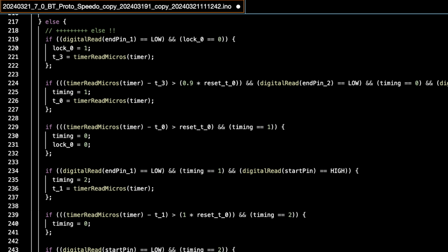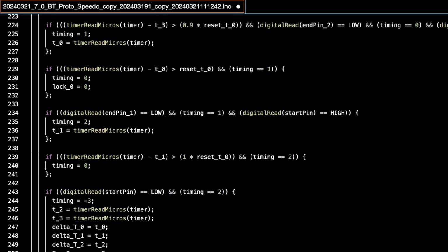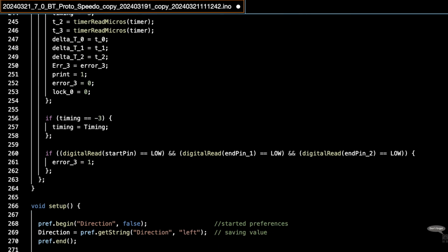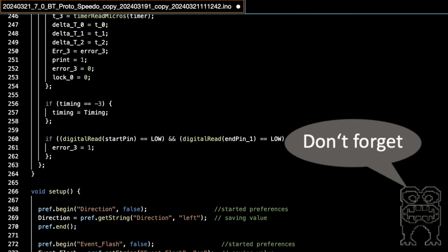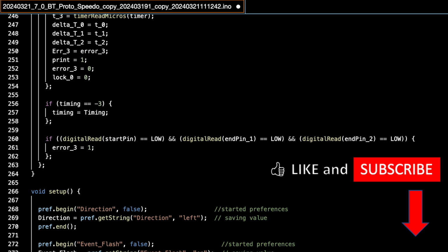For my first trials, I simply sent the speed and the acceleration values to the serial interface after each measurement. This way, I can display the readings with the Arduino IDE's serial monitor or a terminal program. I think I will extend this later to Bluetooth, so stay tuned.